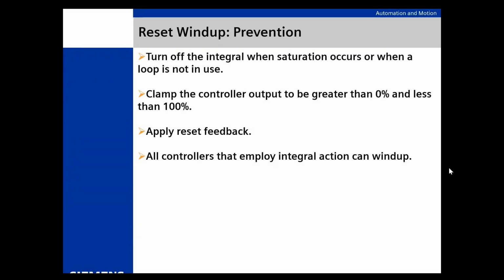So it winds up opening and closing that valve, or turning something on and off and on and off, because remember, it's trying to correct the error. Well, I'm getting zero flow, let's say. Well, I'll keep opening the valve. Well, that didn't work. Now I'm going to close the valve. That didn't work. Now I'm opening the valve. So it doesn't know what to do with that.